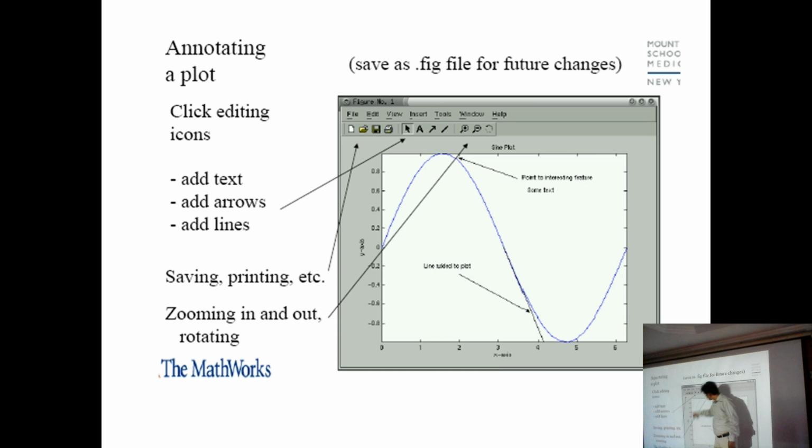Click on the y-axis title, the cursor will automatically come over here, and you can type whatever name you want to give. Similarly for the x-axis, any title, any labeling, any legends, and grid lines. Without using inbuilt functions like grid, xlabel, title, subplot, etc., even using these options you can add them on your figure window.